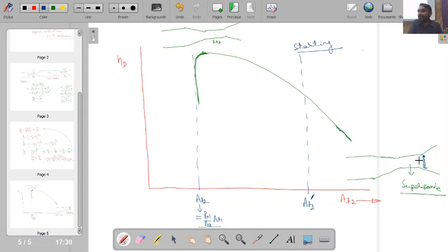Is this point clear? So experimentally, what is observed? Experimentally, it is observed that when we just start a wind tunnel, then a normal shock wave initiates at the nozzle section. That shock wave keeps on traveling, and that particular diffuser section or second throat must have some area A2 dash, which is considerably larger than the area which is required for maximum efficiency of the throat at steady operation. Okay, once the wind tunnel has started. Okay, so that is the reason that the starting area has to be higher.